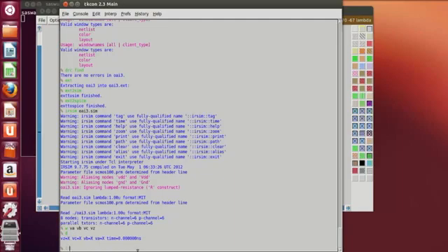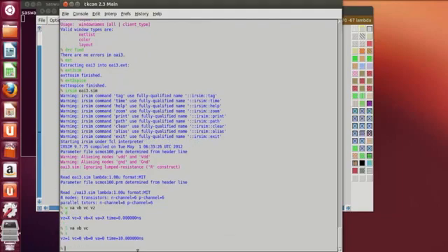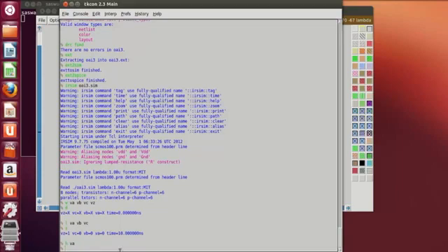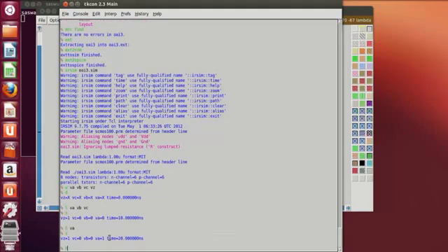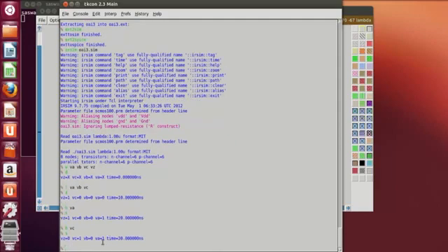If I give low values to VA, VB and VC, then my output will be 1. Since VA plus VB is 0, VA plus VB into VC is again 0, and the invert is 1. If I give high value to VA, the output will remain as 1. When I give high value to VC, the output becomes 0. Why? Since VA plus VB will be 1, VA plus VB into VC will be 1, so the invert is 0.